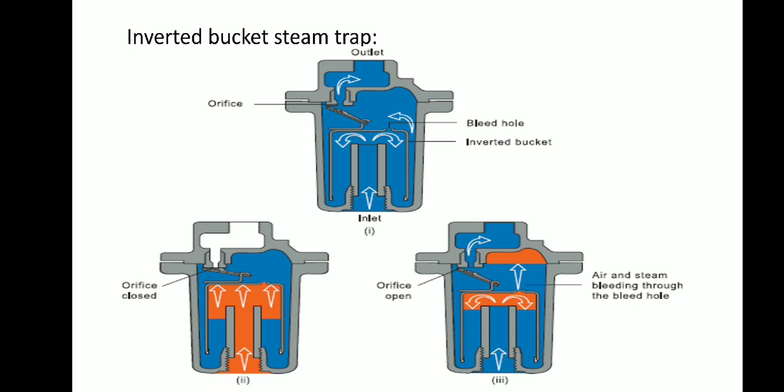For example, turbine drains. The limitation is the small size of the hole in the top of the bucket, which means that this type of trap can only discharge air very slowly. The hole cannot be enlarged as steam would pass through too quickly during normal operation.